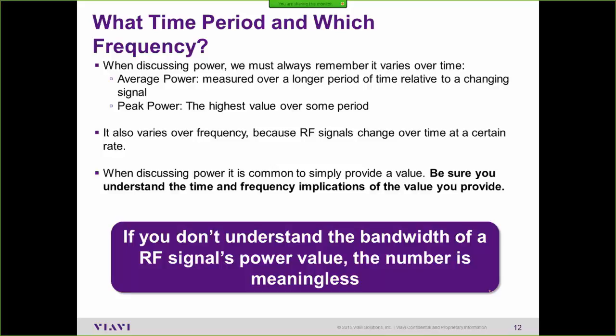But it's really important to understand bandwidths along with the power number because power changes based on the bandwidth of the measurement. And because a spectrum analyzer is a band-specific device, in other words, it's measuring power in specific bands, you really have to understand the bandwidth associated with any power number to make sense of it.